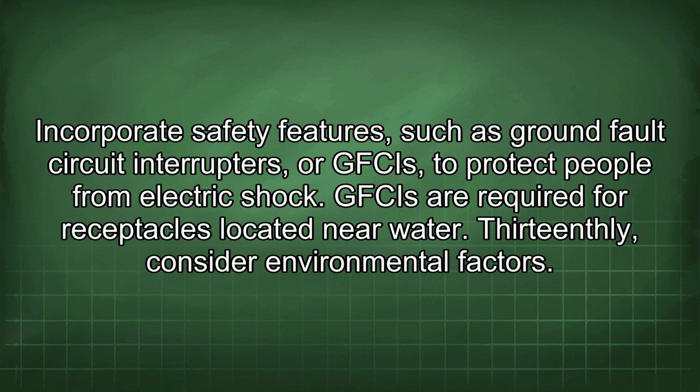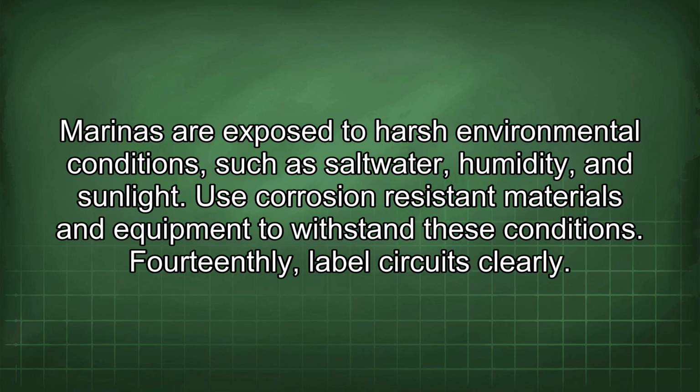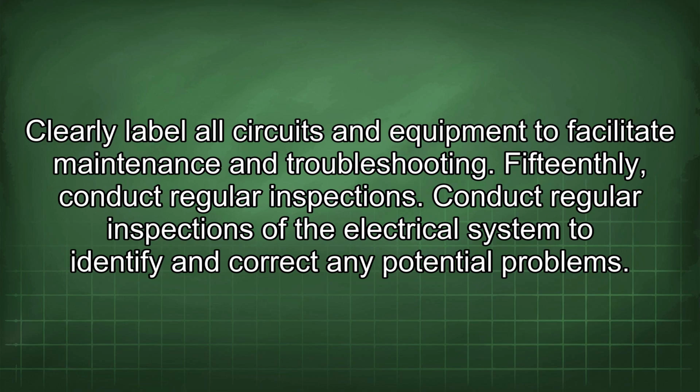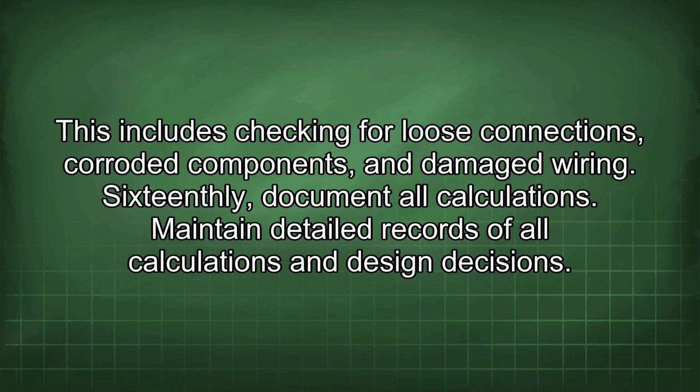13thly, consider environmental factors. Marinas are exposed to harsh environmental conditions such as saltwater, humidity, and sunlight. Use corrosion-resistant materials and equipment to withstand these conditions. 14thly, label circuits clearly. Clearly label all circuits and equipment to facilitate maintenance and troubleshooting. 15thly, conduct regular inspections. Conduct regular inspections of the electrical system to identify and correct any potential problems. This includes checking for loose connections, corroded components, and damaged wiring.